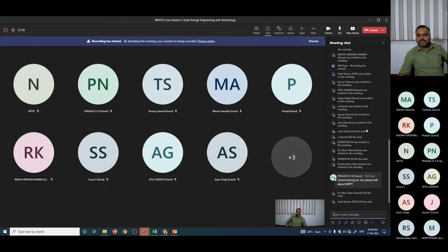Sometimes, for example, if you connect a load which matches the MPPT voltage or MPPT power, then it's fine. You are maximizing with respect to the load which is connected. But sometimes if you have a system but your load is lesser than the PMPPT, then under this condition you are losing the power which is available for utilization. So always our attempt is to operate at the MPPT point. That's why this kind of development has taken place.